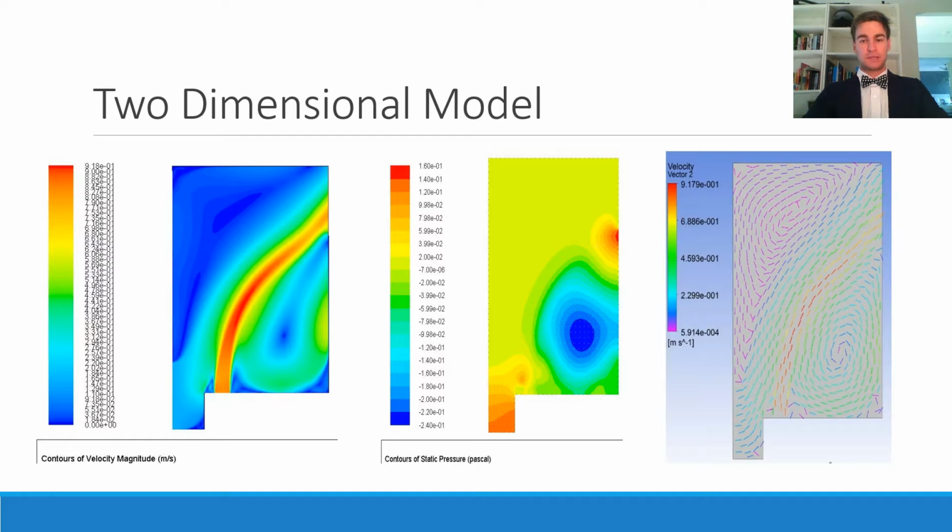The velocity vector diagram on the right provides further information on the flow pattern within the zone. From the flow between the A-recycle pump and the outlet, a vortex is created. Furthermore, short-circuiting may be occurring in this zone. This would be undesirable as it could reduce the contact time between the microorganisms and the nitrogen and phosphorus compounds.